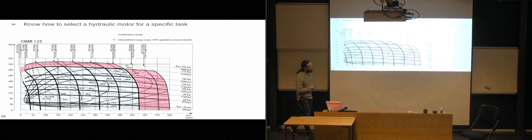Then we're going to quickly go a little bit through the motor again, how we select the motors. Of course, we can do calculations with regards to what amount of rotational speed we need, with regards to the flow rate we have, or if we need a particular amount of rotational speed, for an example, 400 RPMs, then we can calculate how much flow rate we're going to need, just switching around a little bit the one that we calculated for the pump, because it's basically the same.